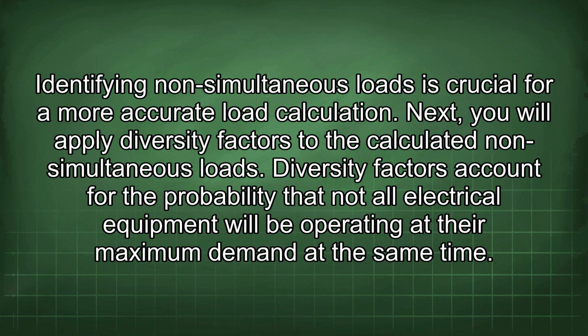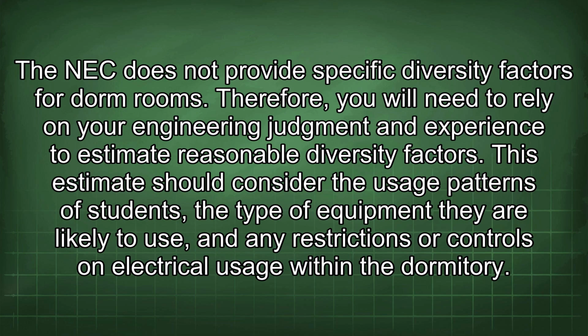Next, you will apply diversity factors to the calculated non-simultaneous loads. Diversity factors account for the probability that not all electrical equipment will be operating at their maximum demand at the same time. The NEC does not provide specific diversity factors for dorm rooms. Therefore, you will need to rely on your engineering judgment and experience to estimate reasonable diversity factors. This estimate should consider the usage patterns of students, the type of equipment they are likely to use, and any restrictions or controls on electrical usage within the dormitory.